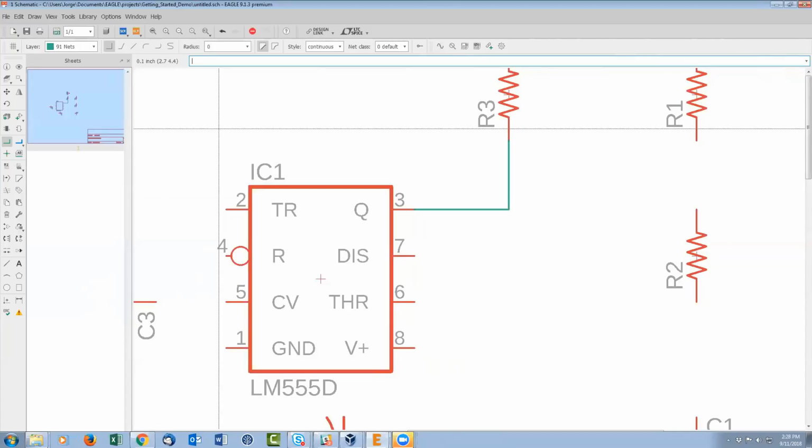in any Eagle library you will ever run into is made to a 0.1 inch grid. That is our 25-year-old convention. If you deviate from that, you can find it difficult to get parts to connect. When you stick to a 0.1 inch grid, everything connects no problem. Okay? So very, very important.